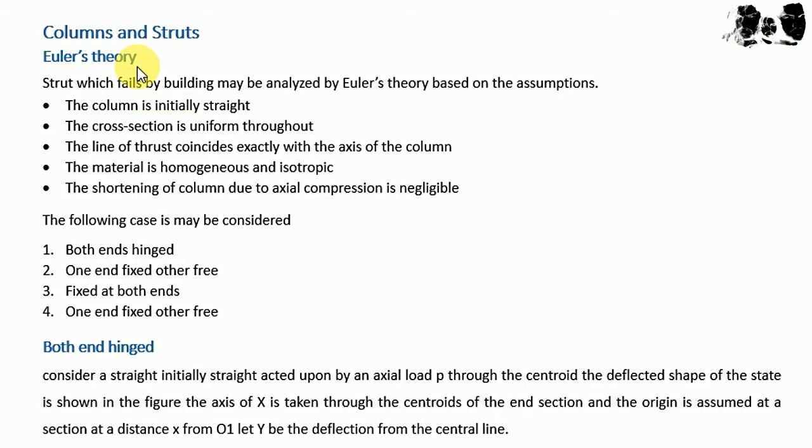Struts are also made of any type of material, but the differentiation between these two is that columns are basically used in a structure in a purely vertical direction. Columns are used along a vertical axis at any point of the structure to support load and transfer it to the foundation. But struts can be used either vertically, diagonally, or at any kind of angle as the structure needs.